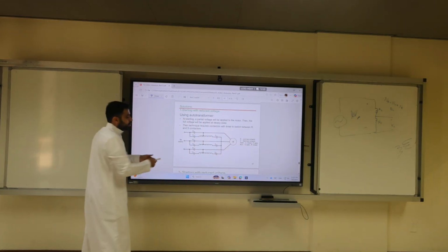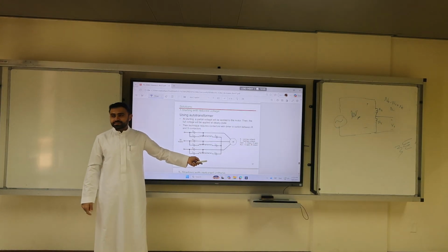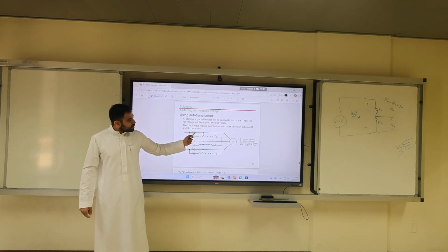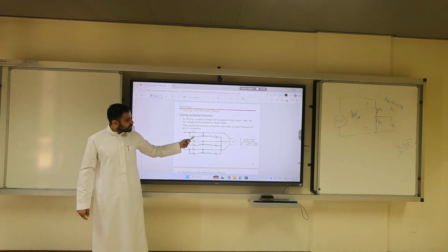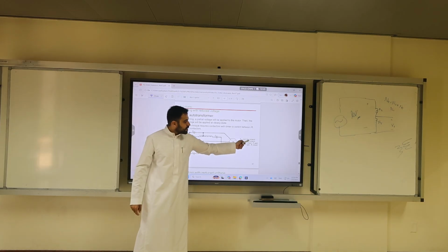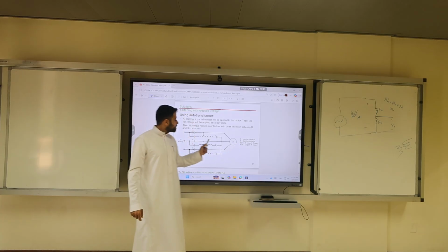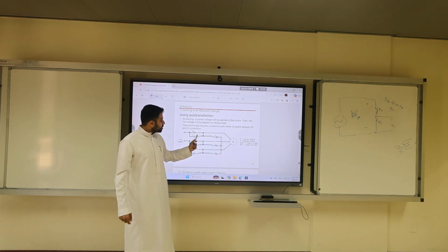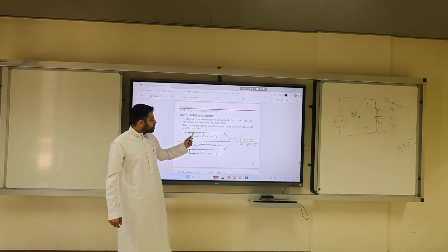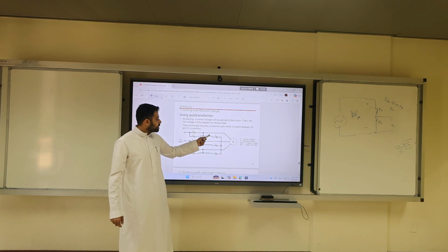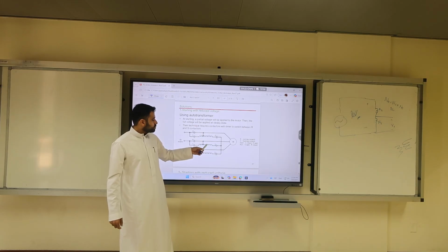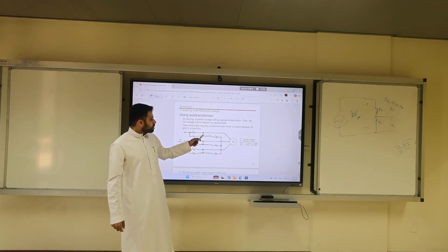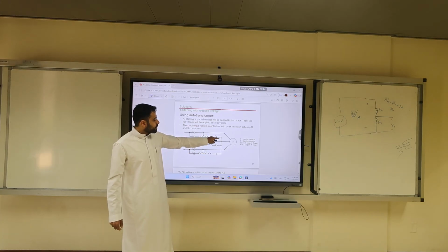So let's see how it looks like. I have 3 coils. Why do I have 3 auto transformers? For each phase. So here we have contacts, R and S. R means running contacts. S means starting contacts. So at the start, close the S, open the R. So you connect your induction machine. Where is it? S is closed, so if I close this S.